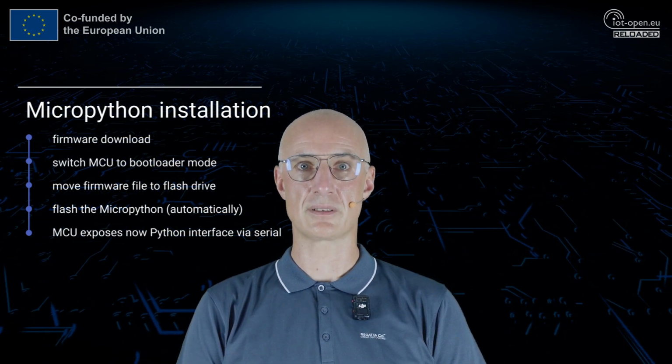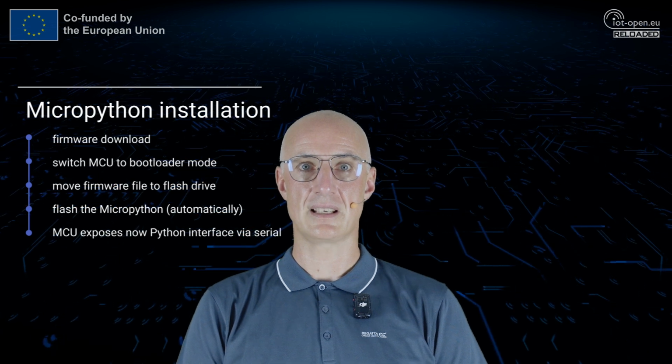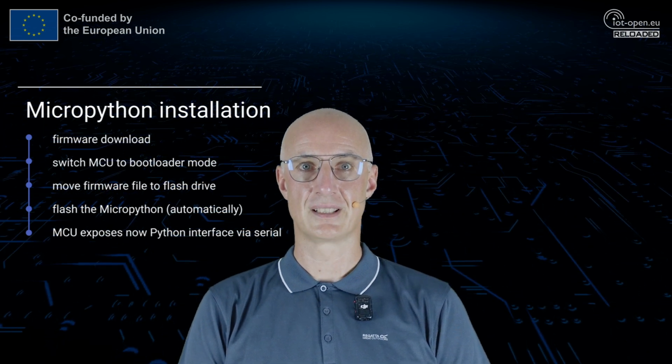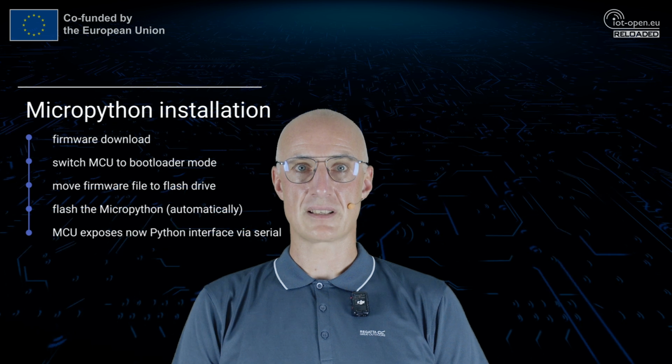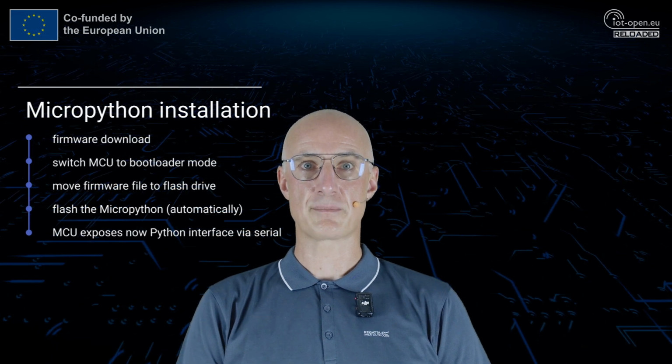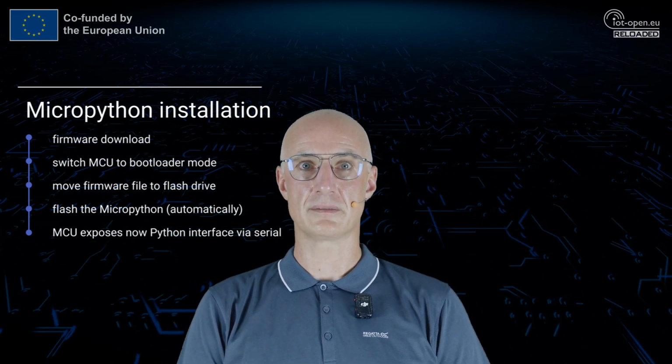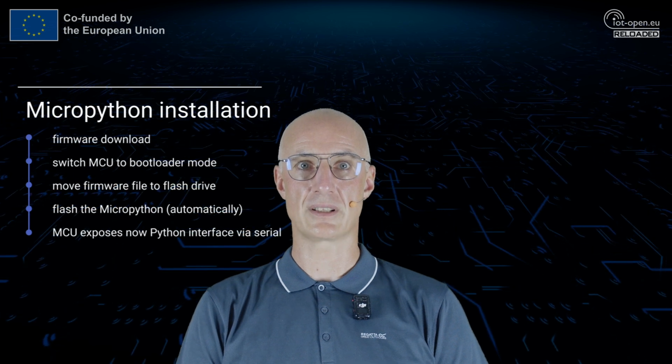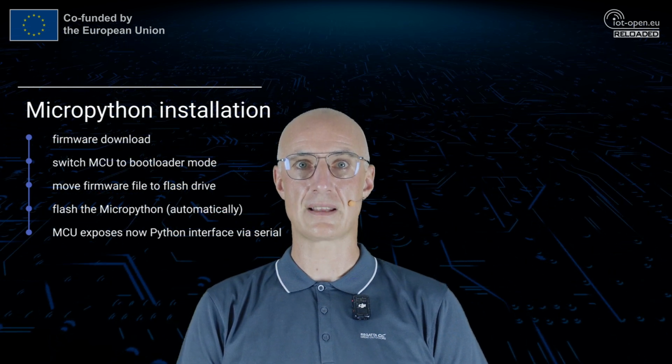The MCU now exposes a serial port that is a Python interpreter interface, as in the case of PC computers. Once MicroPython installs in the device, it exposes an REPL terminal via the serial port, either on the dedicated GPIO or via the serial over USB.